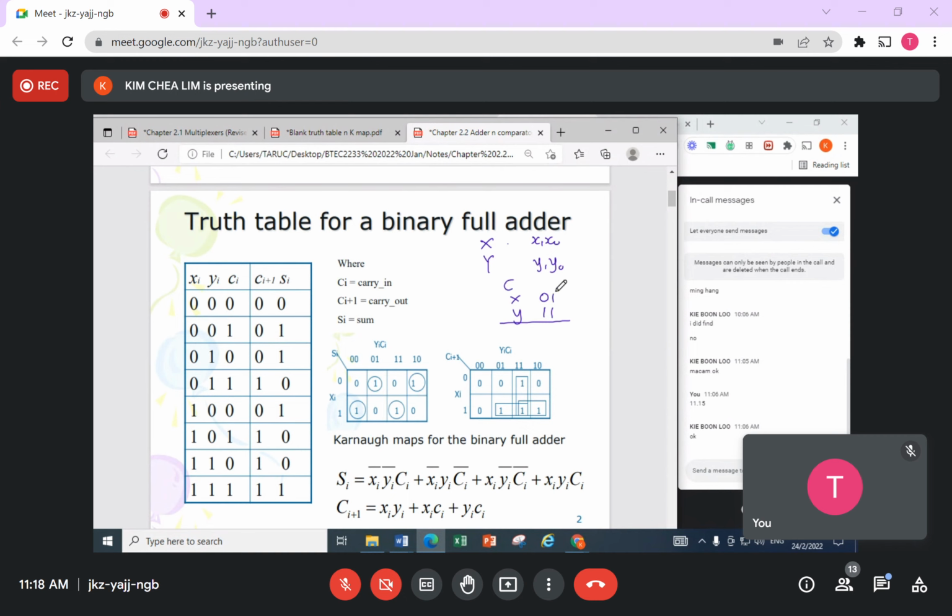Carry, okay, in this case here is a 0. So you can put in here a 0. But the subsequent bit here, actually, I don't know. I have to wait until I finish this addition. All right. So in this case here, you take 0, you add with 1, you add with 1 again, you are going to get here 0.